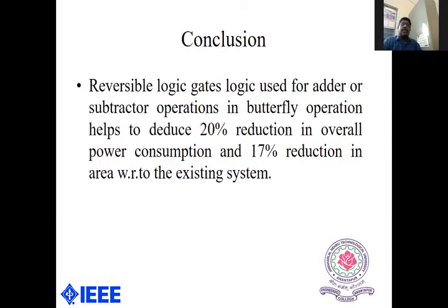So we are concluding that the reversible logic gates, which we use to implement adder and subtractor operations in butterfly operation, reduced a considerable amount of power consumption and area, by 20% and 17% with respect to the existing system.